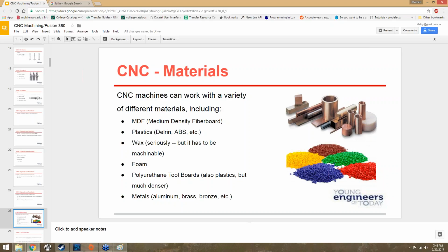It can be possible. The thing is that machinable materials doesn't necessarily just refer to strength. It refers to brittleness or lack thereof as well. You want something that's not terribly brittle, because working with a CNC machine tends to create a lot of vibration throughout the material and a lot of stress on the joints.